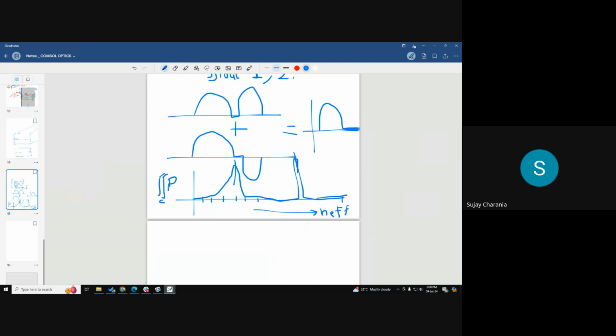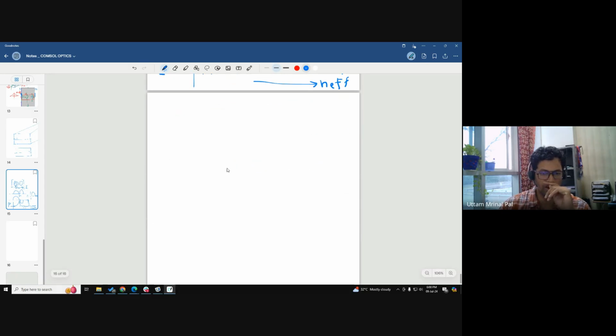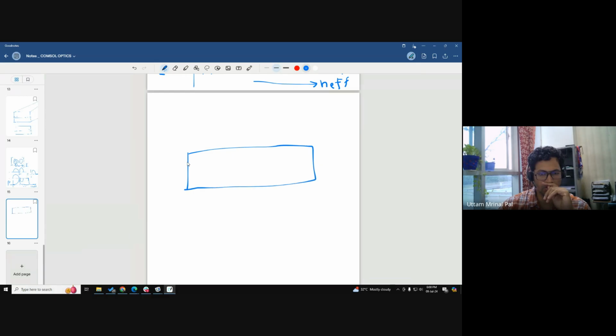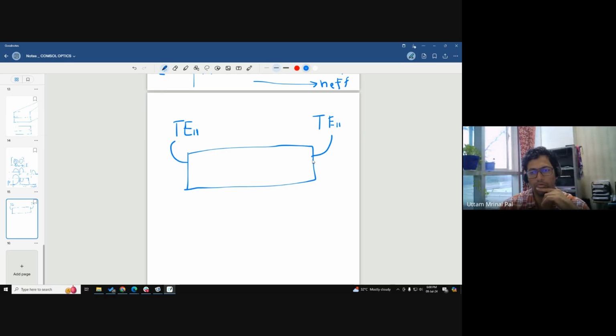So the power would be a little bit tricky, but anyway, if you have a solution, it would be good to know. Yeah, I understand. The way to deal with it, especially for RF microwave problems in the RF module, is this: if you are trying to excite a particular mode, for example the TE11 mode in an RF waveguide, port 1 you give as TE11 mode. At port 2 you also have to give TE11 mode. So only this mode will exist. So the source would be TE11 mode and the output would also be TE11 mode. Even though other modes are being generated and present, this port condition will only cater to this particular TE11 mode.